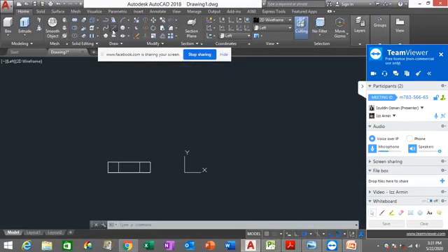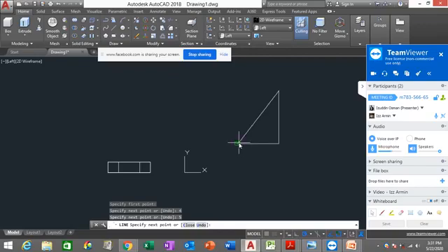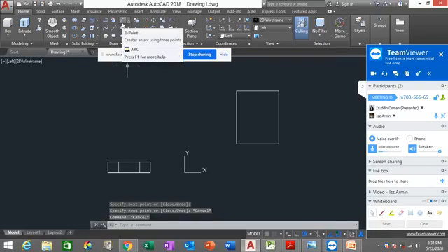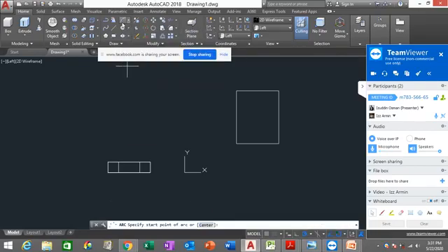So I'm going to draw this. I'm going to click line, click here. This one is 4. The base is 4. The height is 5. By referring to the course manual, I can press escape to terminate the balance line. Click arc, type C, enter. So this is my start. So I'm going to click start here. Click. So this is my center.